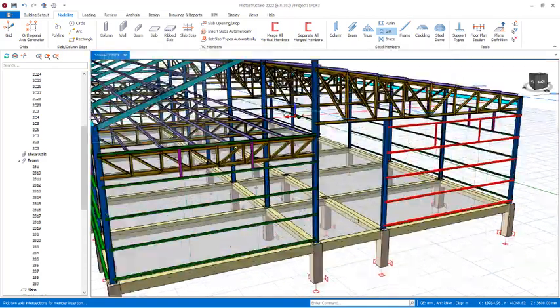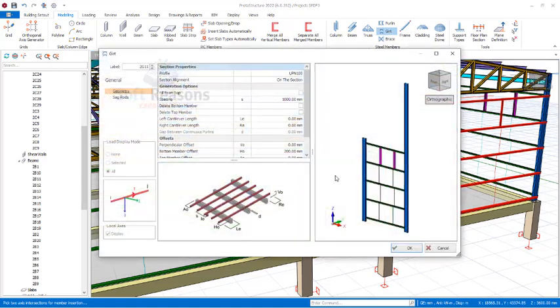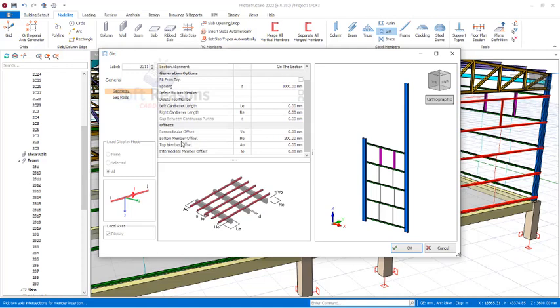Okay, options. Then for this entrance, we'll also be having a gate, but it's not going to cover the whole of this place. So I will show you how to do that. Pick this one and this. All right, so in these provisions now, we are going to come over for where we have bottom member offset. All right, the bottom member offset, we are going to make it 2350 right there. Okay, then for the spacing of this member, we will change it to 300 spacing right there. So we having something of this kind, or let's just make it 400 spacing.